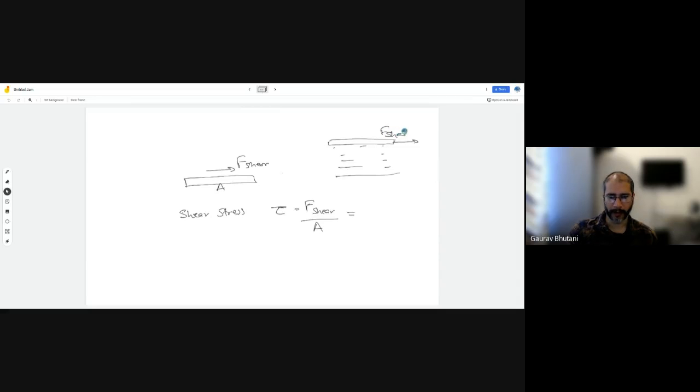So if that wooden plate which is floating on the surface of some liquid, and you start moving that plate, that plate will apply some sort of friction or shear on the fluid, and that fluid will also start moving with it. So this tau can now be written as the viscosity mu times du by dy, where u is the x component of velocity and y is the coordinate, which is in the direction of the normal of the plane. So this is the normal.